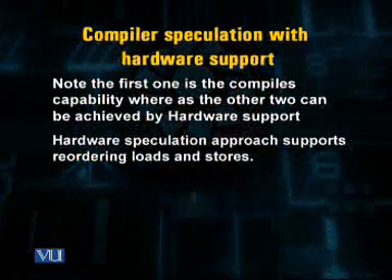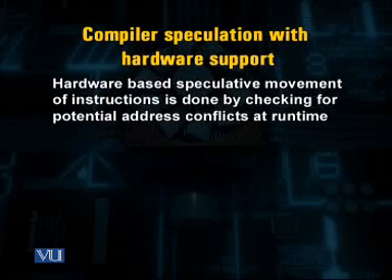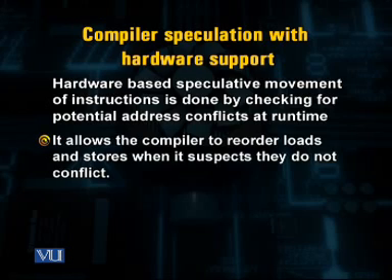The hardware speculation approach supports reordering the load and store instructions. Furthermore, the hardware-based speculative movement of instructions is done by checking for potential address conflicts at runtime, and it allows the compiler to reorder loads and stores when it suspects that they do not conflict.